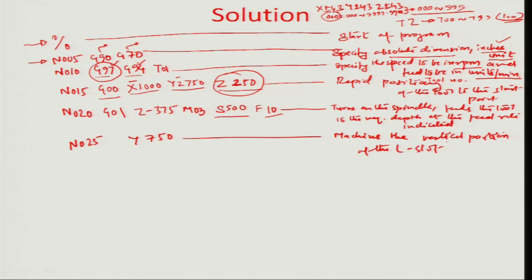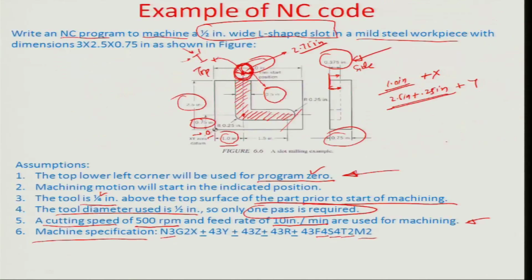So once this machining is done, the tool is now at a new position located somewhere here, and it is centered about this 0.75. The other thing we need to ascertain is that the tool goes in this direction from the current location, 1.000 inches, to 1.500 inches, traversing by another 1.500 inches.